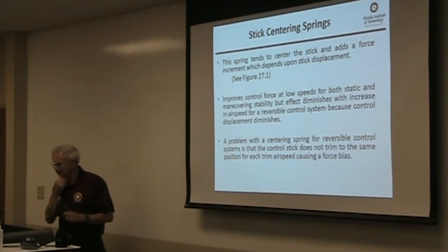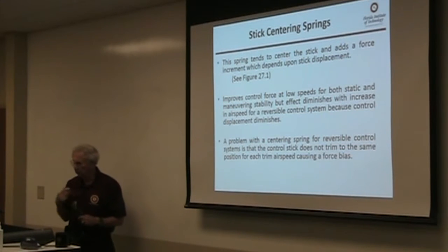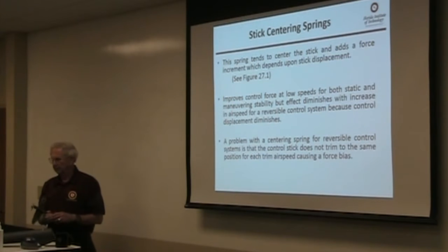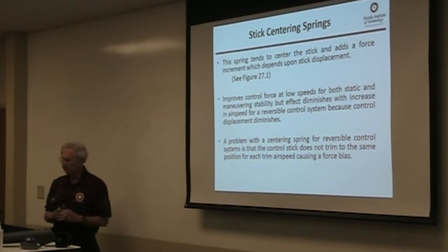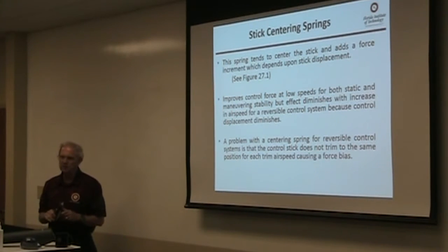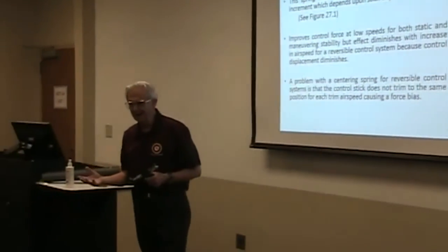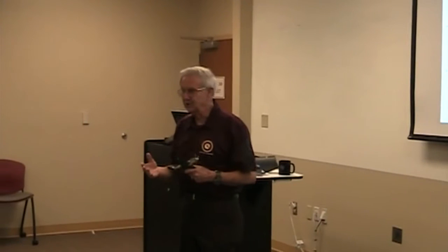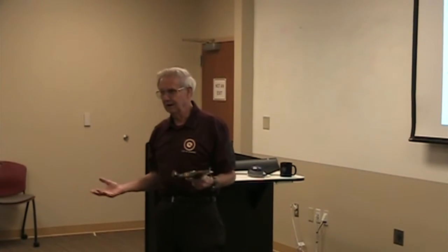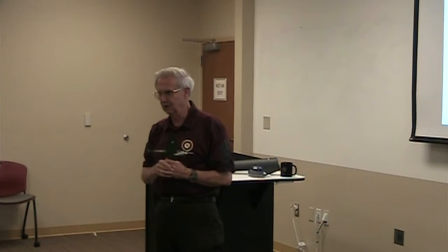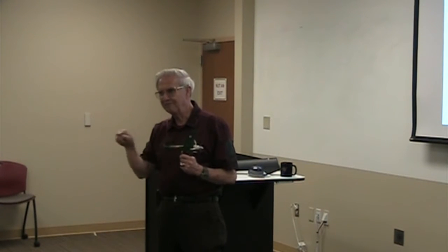Well, that improves the control force at low speed for both static and maneuvering stability, but the effect diminishes with an increase in airspeed. If you notice from our plot of elevator position, when we did longitudinal stability, what did that plot look like as the speed increased? Got pretty flat, didn't it?